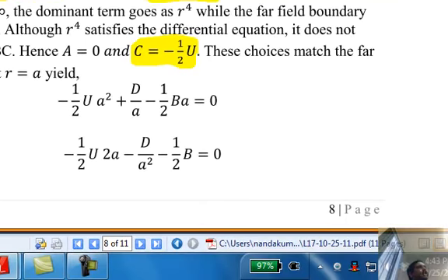But remember, we did have 2 boundary conditions in the far stream. The far stream was specified as u, but we decomposed that into Vr and V theta. We really had 2 conditions for the 2 variables. The next set of constants, b and d, are evaluated at a. At r equal to a, psi is 0. At r equal to a, d psi dr is 0.